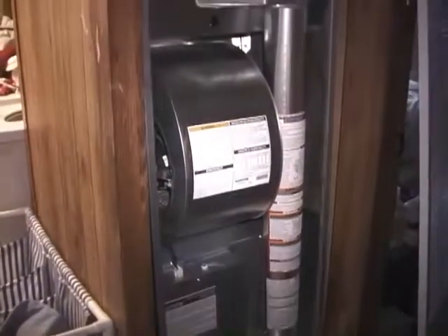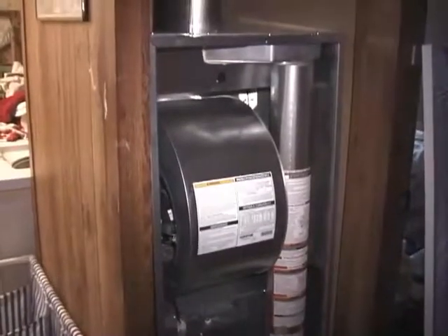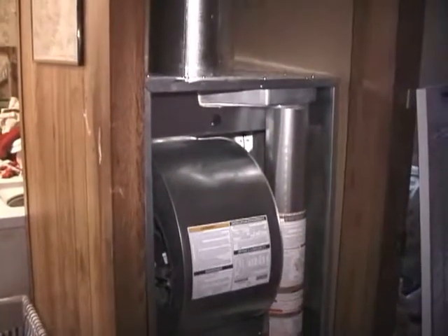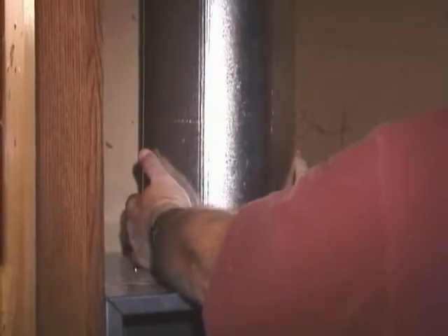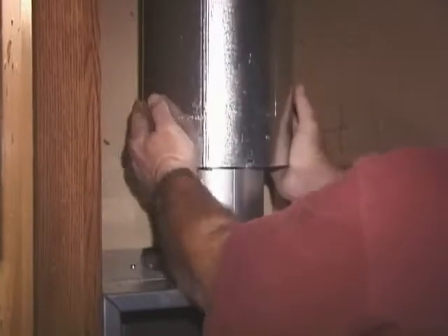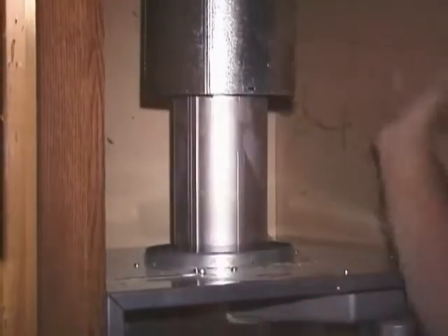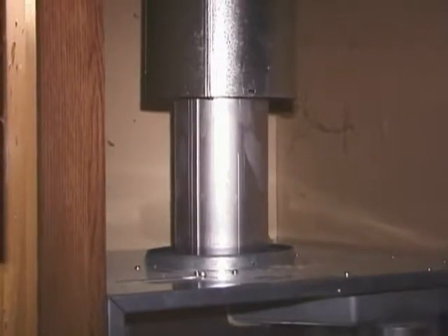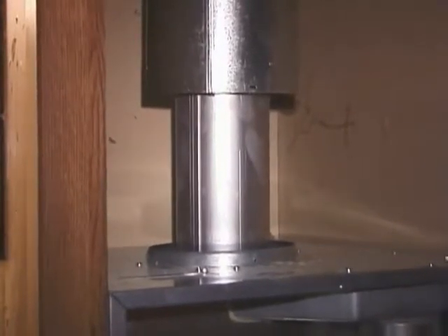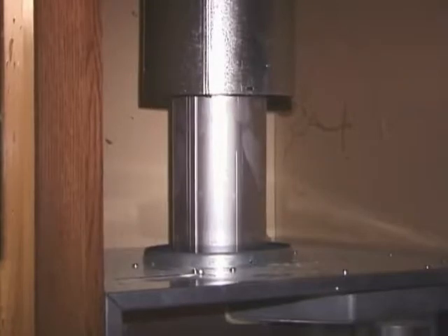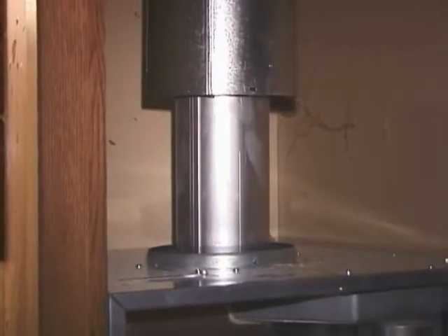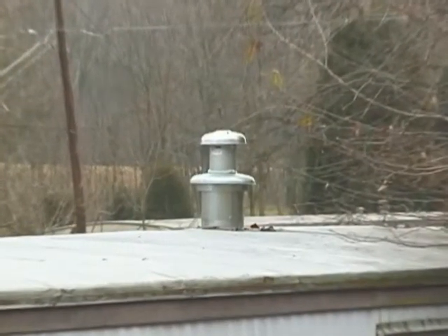This is the type that is required for use in mobile and modular homes. This type of furnace vents directly through the roof vertically and typically does not allow the use of any elbows or offsets. All of the combustion air is supplied from outside the structure through either a duct through the floor at the base of the furnace, or as you see in this example, from above through a double-walled vent system. The flue products exhaust through the center pipe and exit from the top of the roof cap.